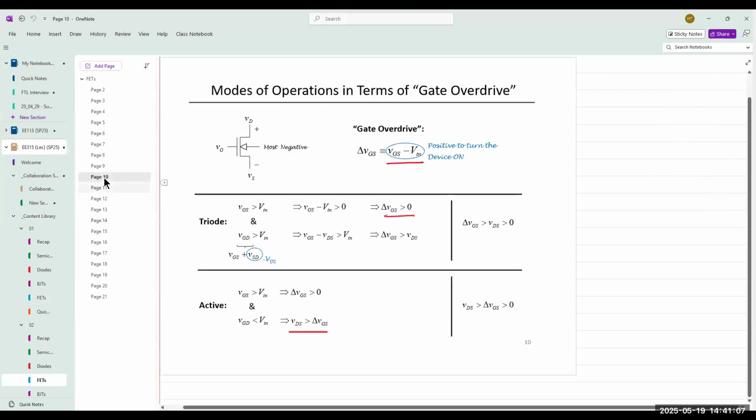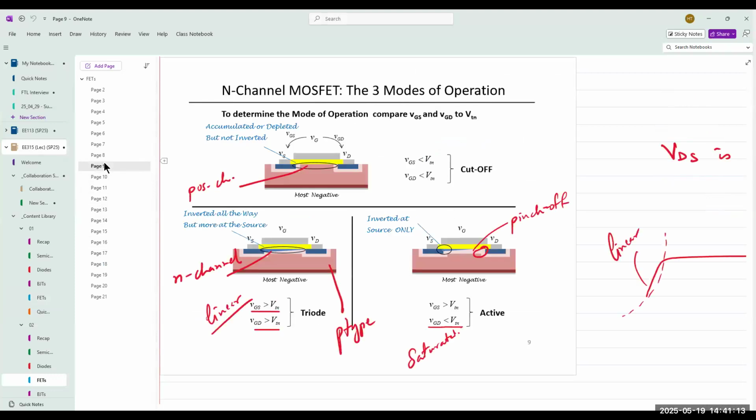So we'll look at the basic device physics, how to establish a channel in a MOSFET and how current would flow through. Again, this is a brief recap. Essentially, we have either two N-type regions or two P-type regions, separated by a certain distance. When we apply a voltage, we can create a channel that joins these two regions.